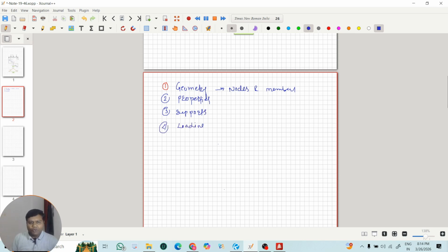Okay, so whatever loading we are applying on our particular building or our model, that we have to define over here. And as we discussed, so many loads are there, like we know dead load, live load, earthquake load, wind load. So these are the loads, and STAAD considers all these loads as load cases. So whatever problem statement we are discussing over here, we are considering all load as a dead load. Okay, so one by one we will discuss how to add dead load, live load, wind load, earthquake load, everything that we will discuss in upcoming videos.